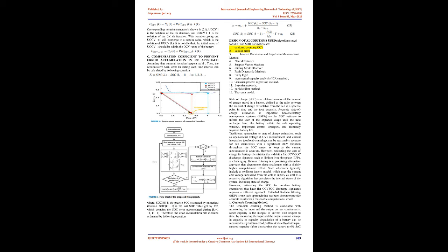Before the proposed approach is implemented, whether the battery has been steady should be assessed. As mentioned previously, at the steady state of a battery, the current flowing through the capacitors of the RC circuits in the model is negligible. That is to say, it can be assumed that the measured current I only goes through RP1 and RP2. Therefore, the following criterion could be formulated, where S1 and S2 are defined as the steady coefficients, reflecting the divergence degree of the dynamic voltages from steady state.